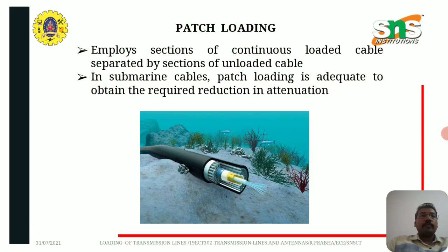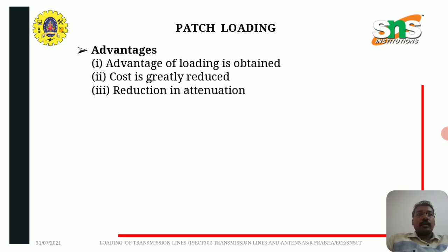Patch loading. It applies sections of continuous loaded cable separated by sections of unloaded cable. In submarine cables, patch loading is adequate to obtain the required reduction in attenuation. The advantages of loading are that cost is greatly reduced and attenuation is reduced.